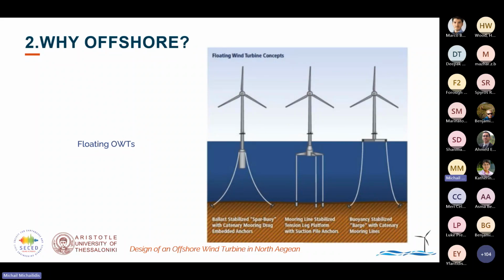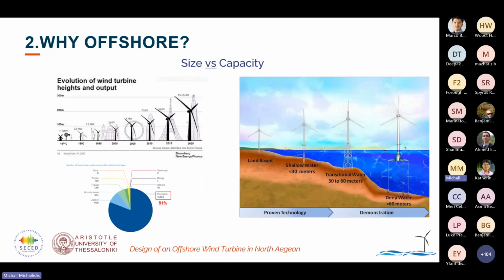On the other hand, there are some floating offshore wind turbine concepts. The spar type has been the first one to be implemented, like the Hywind project, the pilot one in Norway, and later around the UK. We have also the tension leg platform and the semi-submersible concepts for reference.